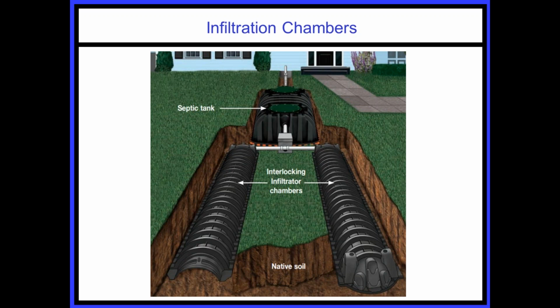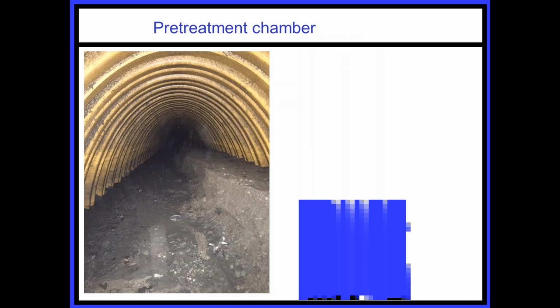This technology has been around way longer than the chambers that are currently being used today for stormwater. The difference between the septic chambers and the stormwater chambers is the septic chambers are not intended for traffic loads, for deep burial applications, meaning more than a couple feet deep. The stormwater chambers are structural chambers intended generally to be under paved areas or areas that may have live loads. And so that's the main difference, but the concept is identical to this.